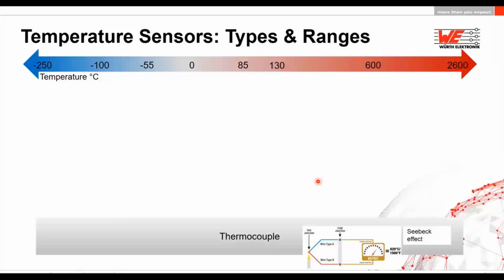Basically, the thermocouple uses a reference temperature as a cold junction, and the hot junction is the temperature where you measure with respect to the temperature of the cold junction. On the other hand, this kind of sensors are highly nonlinear. Also, they are not stable and the accuracy is not so good. But the fact is that they can be used over a wide range of temperature.